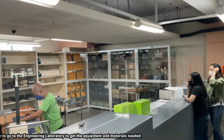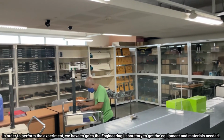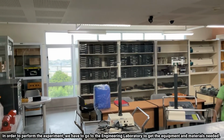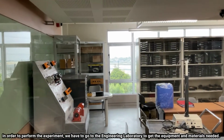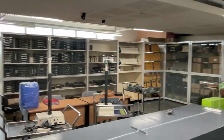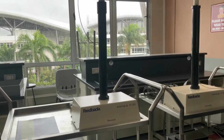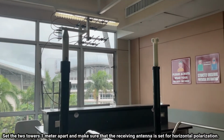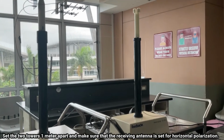In order to perform the experiment, we have to go to the engineering laboratory to get the equipment and materials needed. Set the two towers 1 meter apart and make sure that the receiving antenna is set for horizontal polarization.